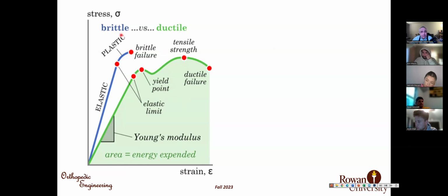But a material that has a short plastic range, it has an elastic range and suddenly enters the plastic range and then the breaking point. And usually in these materials, the modulus of elasticity, or the slope of this curve, is very high. This material is called brittle. They do not undergo plastic deformation before failure, or at least a very small plastic deformation. They have a small elastic change, and then suddenly they enter the plastic, and then they fail.